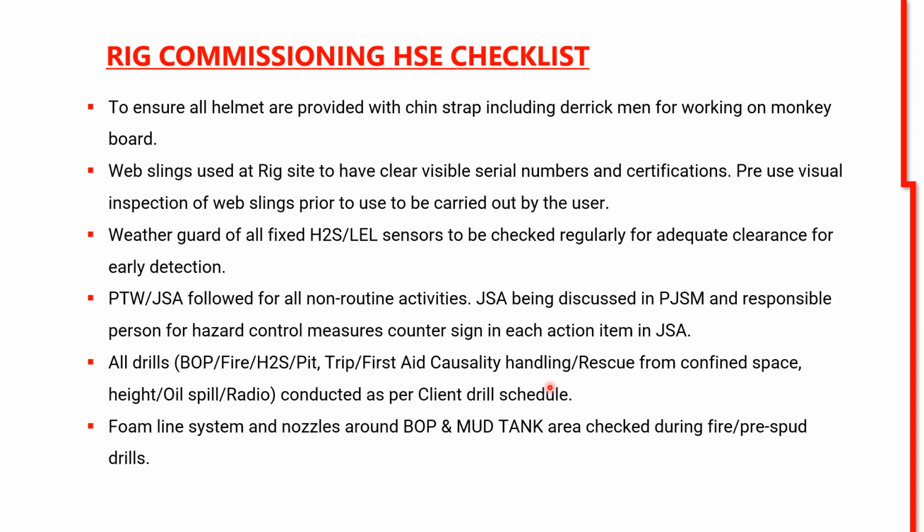If it is found by the client representative or company man that the rig crew are not capable enough, are not responding to the emergency in a correct way or in a specified time, then he advises a higher frequency, repeating the drills more than the client's advice. Foam line system and nozzles around the BOP and mud tank area checked during the fire or pre-spud drills.